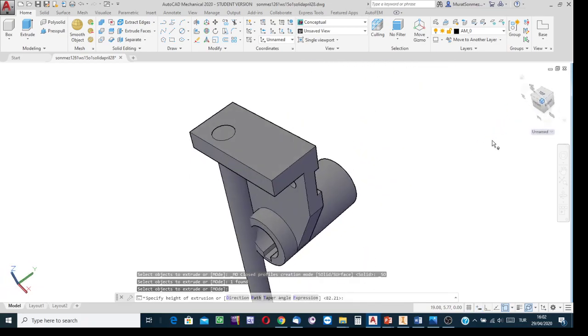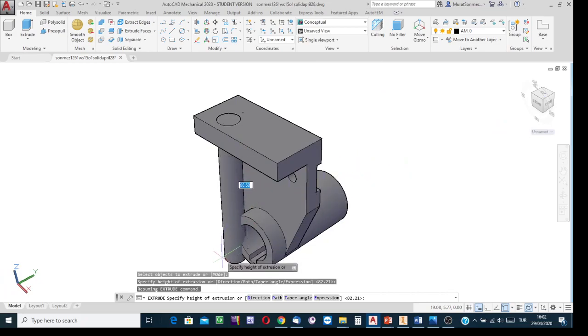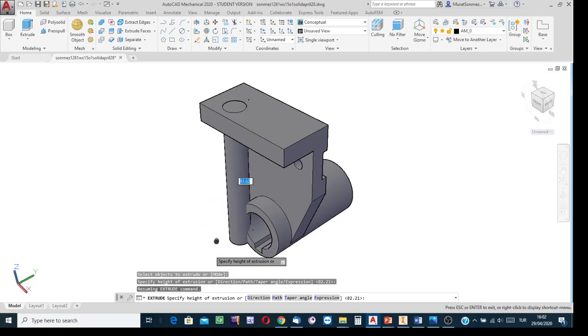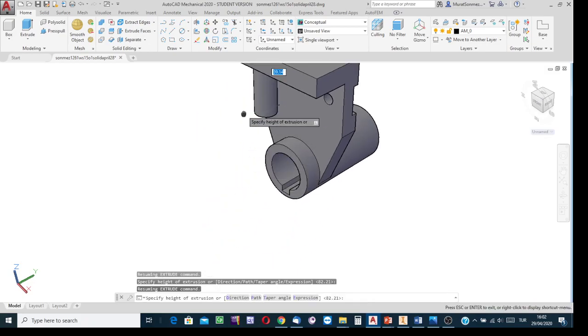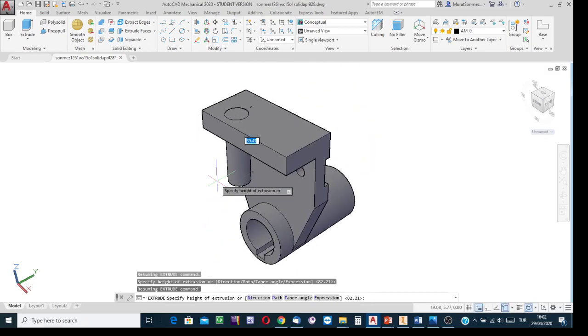In extruding it, do not extrude it arbitrarily. In Inventor, to create the hole, you apply the hole process and say that the ending surface is the opposite side of the rectangular prismatic extension. To indicate the ending surface, select the two option and indicate it. If you watch the previous video record, you can see what I mean.